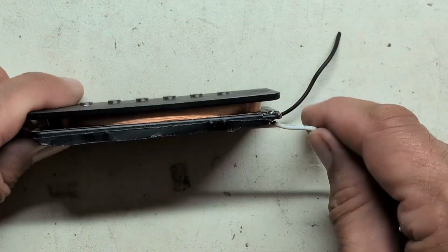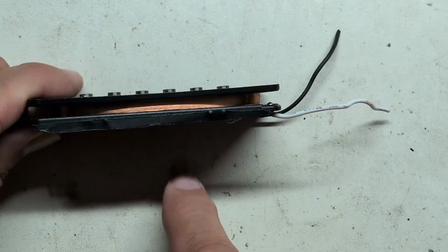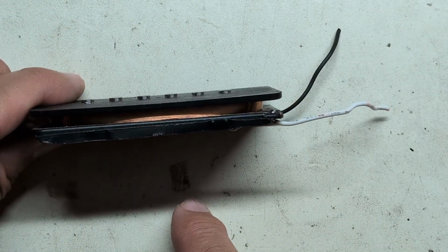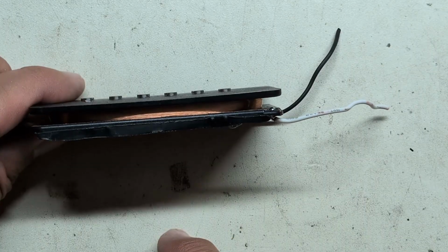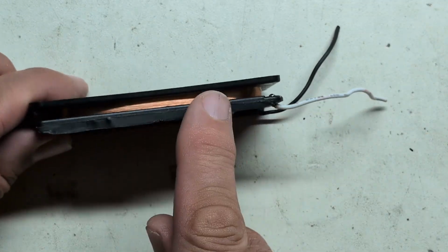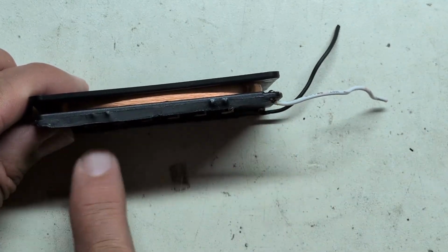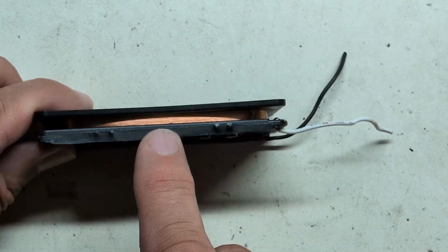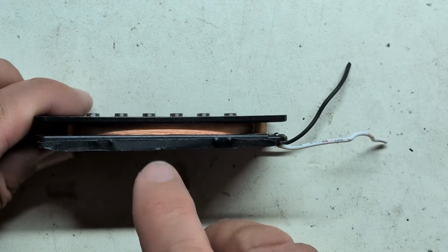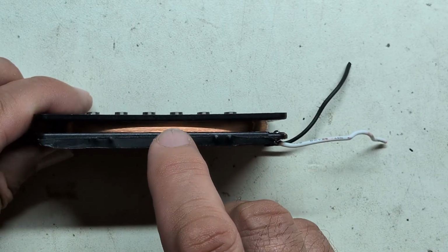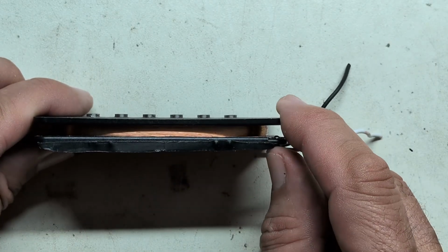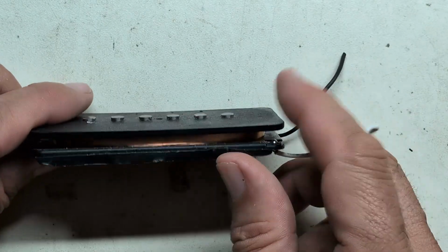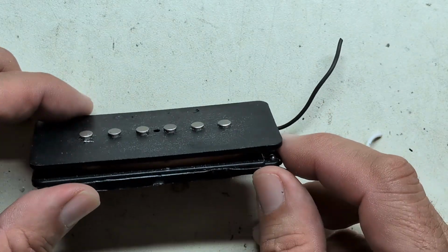One is, first of all, it's a long coil of wire. So the longer the coil of wire, the more wrapped the pickup is, the bigger the resistance is, because there's more wire. Secondly, any kind of cable or wire that's wrapped like this has an inductance. And then thirdly, you can see inside there's lots of wires, and they're all very close together. And that closeness creates what we call a capacitance as well. So we've got three elements. We've got resistance, we've got capacitance, and we've got inductance.